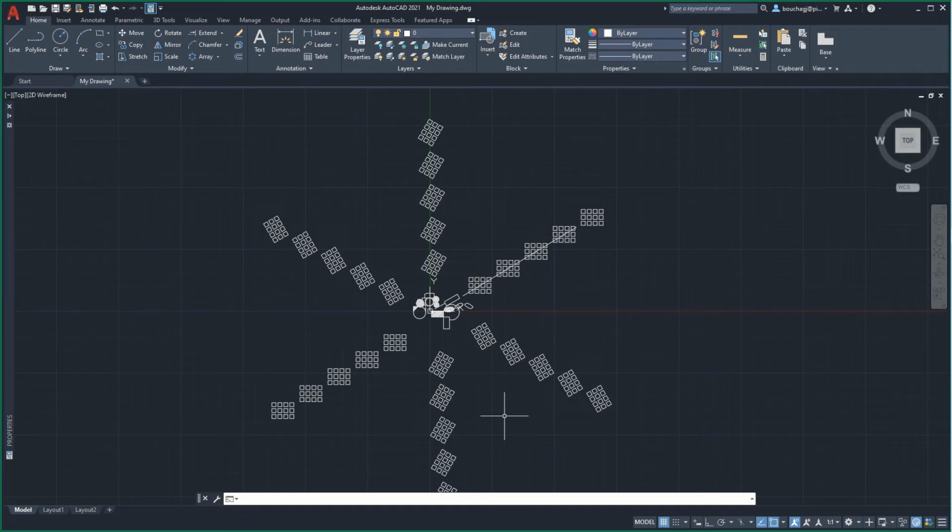Enter the rectangular array command and select the new 4x4 square at the prompt and hit the Enter key. Note that the default rectangular array setting is 3 rows and 4 columns. There are several command options within the command line in squared brackets to be explored. For the moment, we will accept the default arrangement and press the Enter key to exit the command.